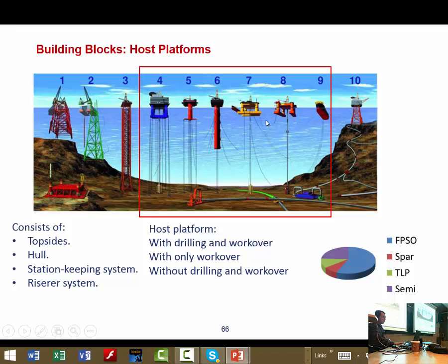To reduce that, this is just a standard solution for a circular body in high-speed flow. These spirals around reduce these shedding vortices, and then reduce this lateral motion. And even on the risers, if you have a high current like in the Gulf of Mexico, they still use these spirals on the riser and the pipe to reduce lateral motion.